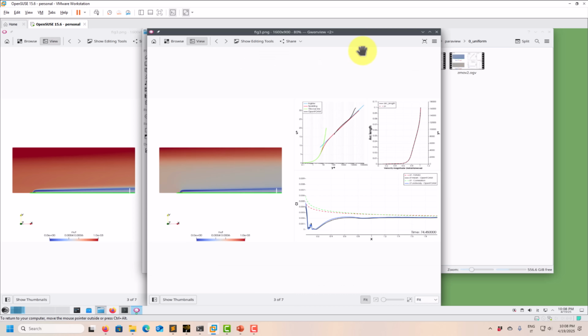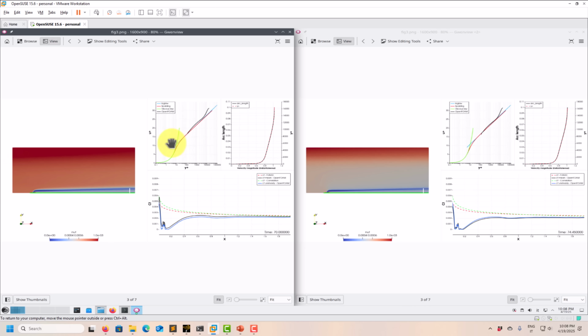So both of them are wall modeling. Remember that the Reynolds stress models in OpenFOAM are wall modeling. And you have here, this was the initialization. This one is from the uniform one. So in theory, the one using initialization should converge fast because you don't have that initial transient. Okay, so remember, you start from 0, you have an initial transient. So you are saving that, okay? So you can get a steady simulation very fast, some coarse one, and then save that initial transient.